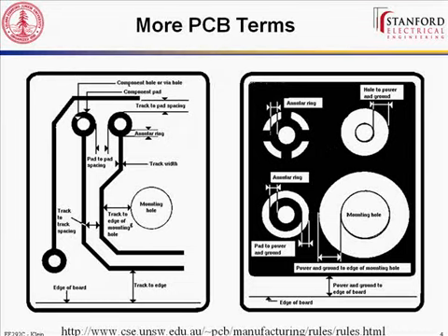And you also get a capacitance between these two plane layers, between the ground and the VCC, that helps keep your power rails higher. It helps bypass. So that's just kind of an added benefit that you get from the two plane layers being close together. But in general, your plane layers are going to be for a signal that's distributed to many places like power and ground. There are very few other signals that you would have a plane for.